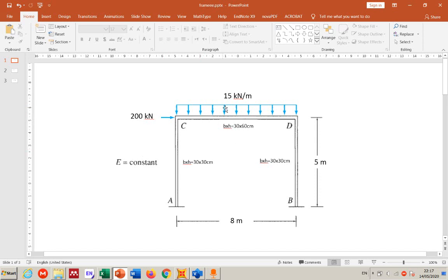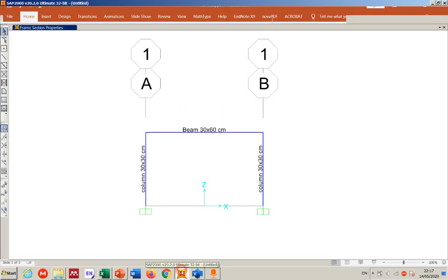The idea of separating them: if you separate those loads, the result you can show only for this one, or you can combine them together as well. That's why it's sometimes recommended to define the live load alone and dead load alone, because you have the analysis for dead load, the analysis for the live load, for the wind alone, then the combination between them, all of them together, so you can see all the results separately.